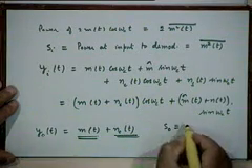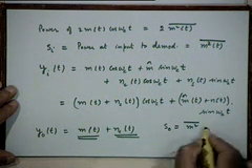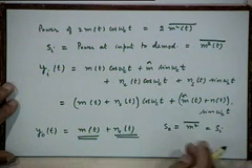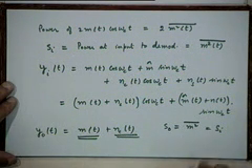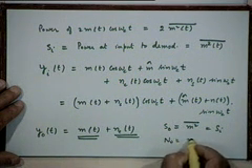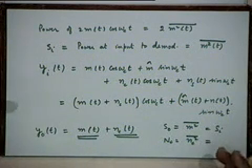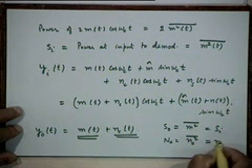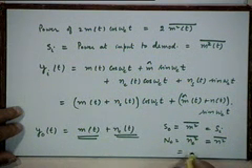So, what is the output signal power? What is S sub O? Once again m square bar, which is equal to S sub I, right. So, output signal power once again as in the earlier cases is equal to S sub I, and what is the noise power? It is the expected value of n sub c square, which once again is equal to expected value of n square, if you remember, and that is equal to once again how much?